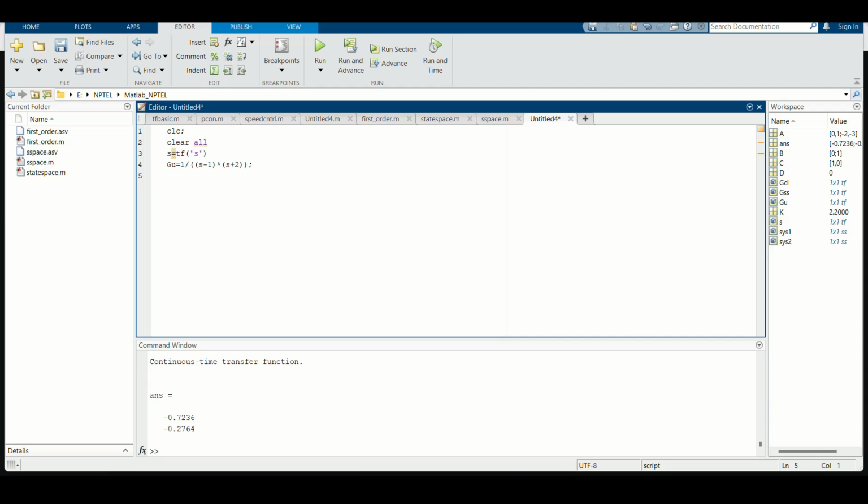Another way is to just use the auto tuning method of MATLAB. So how does this auto tuning work? The command that we use for this tuning is pidtune. I am interested in getting a PI controller, that is a proportional integral controller, for it. I will explain the meaning of this syntax.